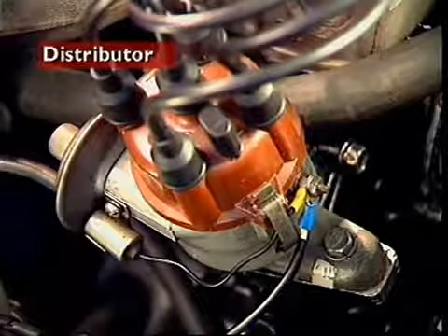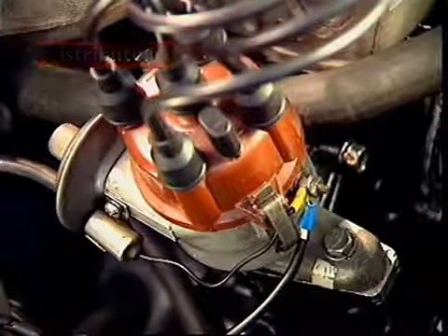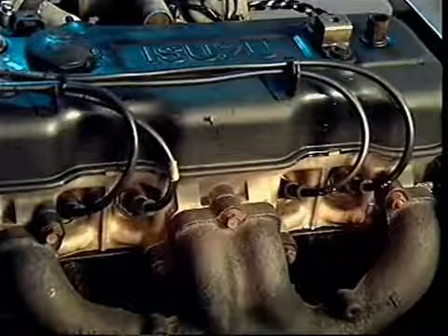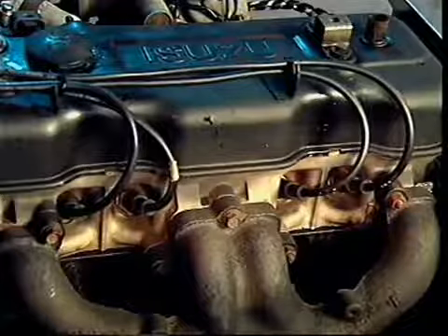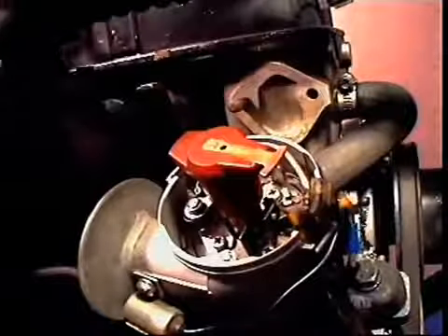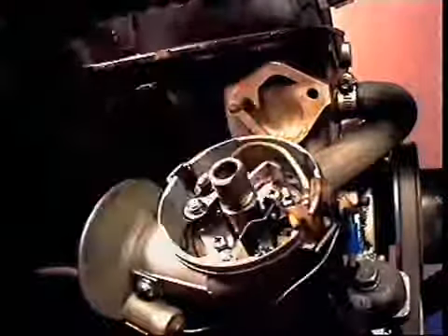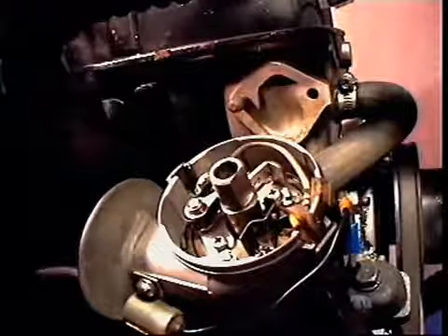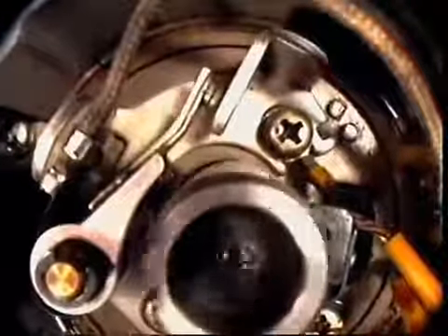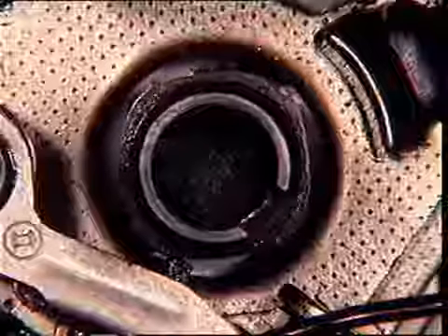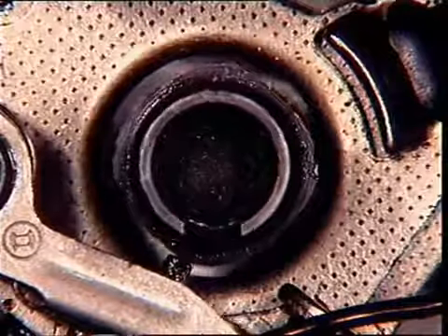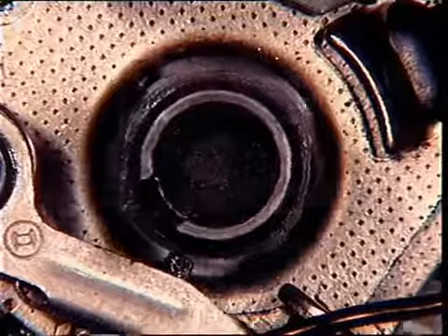The purpose of the distributor is to distribute the high-tension voltage surges to the individual spark plugs in the correct sequence and at the correct instant in time in the engine cycle. Since each high-voltage surge is triggered by the opening of the primary circuit, it is convenient to locate a single set of contacts in the distributor housing and operate them by lobes formed on a cam which is driven by the distributor shaft. The number of cam lobes corresponds to the number of engine cylinders.